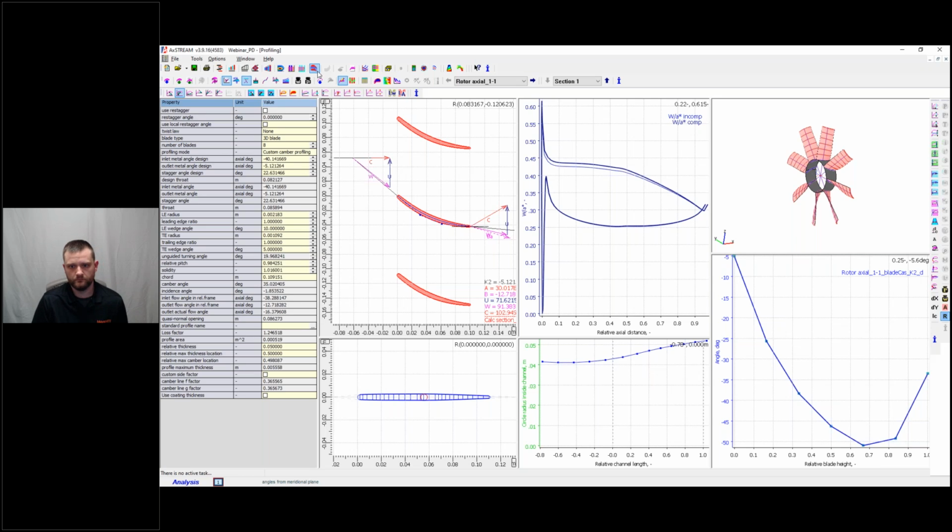Okay, so the next thing, further down the road, would be the profiler to adjust the found geometry, because it just gives you an initial geometry and fine-tuning to accommodate off-design conditions will be necessary. Here in the profiler, you can see the various characteristics on each profile section: inlet angle, outlet angle, stagger, you name it, it can all be found here and changed. There are various features which allow you to change the geometry as well. You can see updates right away.